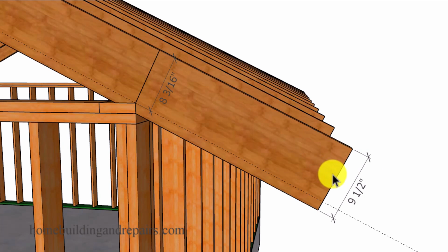And of course, this brings me to another problem with the seat cut length, especially when referring to heavier roofing materials like tile that might require wider lumber for your overhang, or loads from snow sitting on your roof for a long period of time that might require a wider overhang. I will not be able to provide you with information for those lumber sizes. You'll have to check with a structural engineer for that.